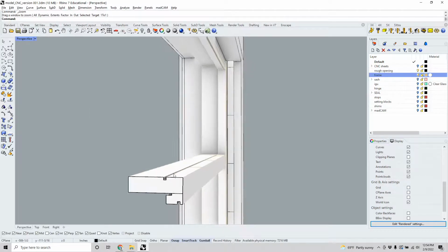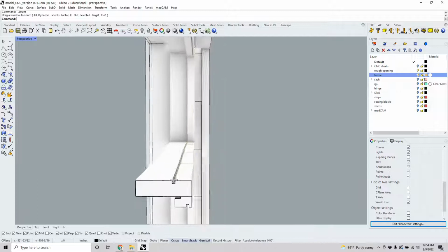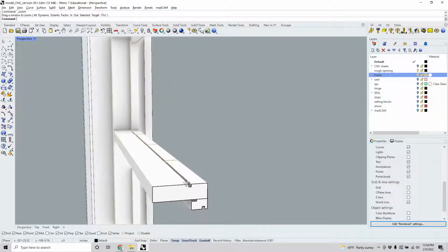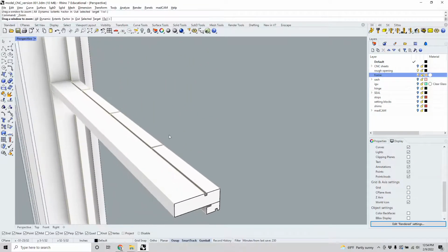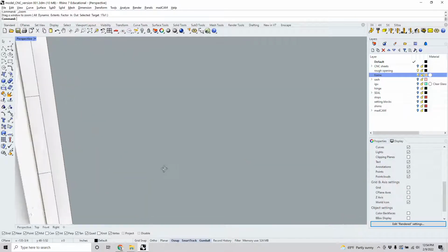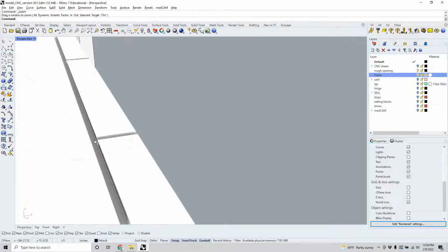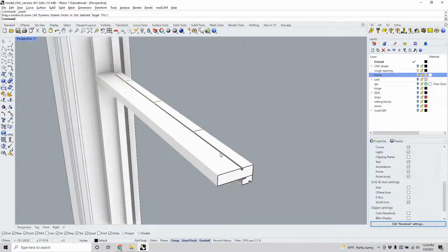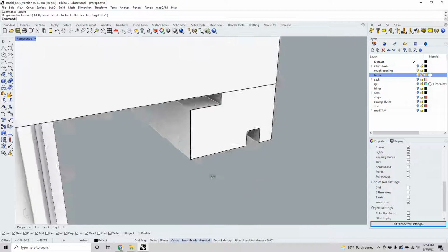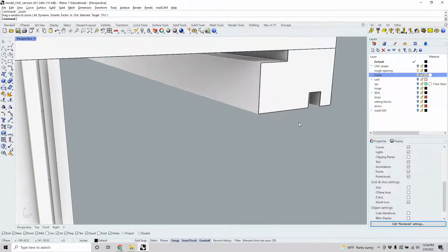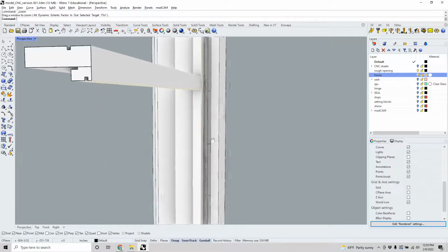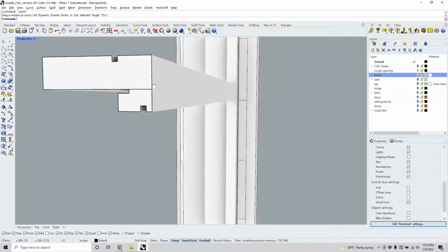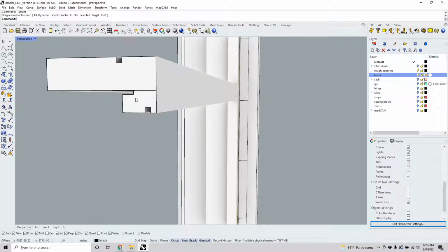At this intermediate sill, I also have a channel built on to the top of that sill. Again, that can collect any water that seeps back there. And these little channels are sloped, moderately, so that they can purge that water out, these little weep holes. At the bottom, similarly to the top, there's another little drip edge, again, for water to drip off of.